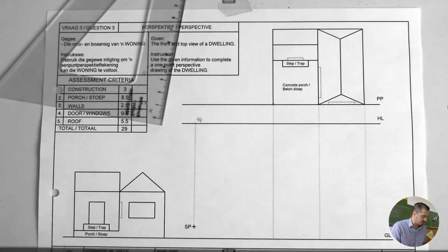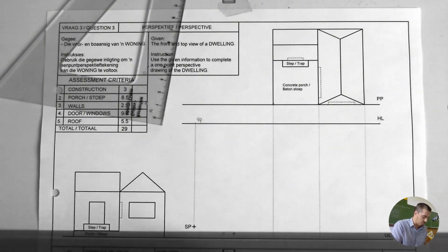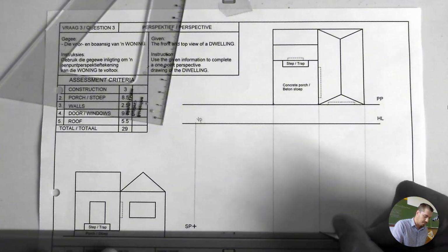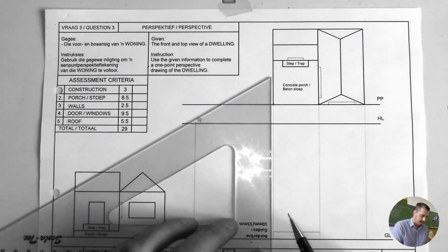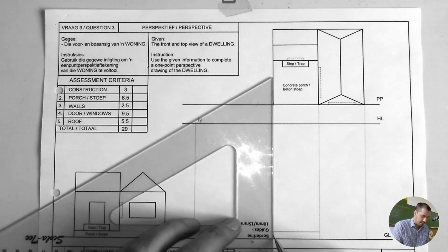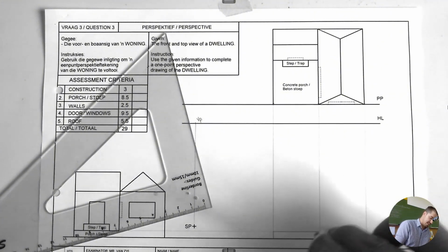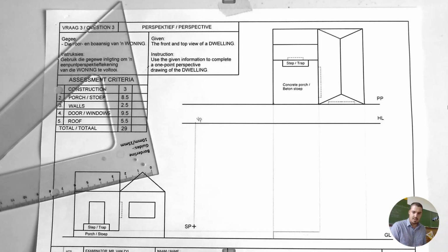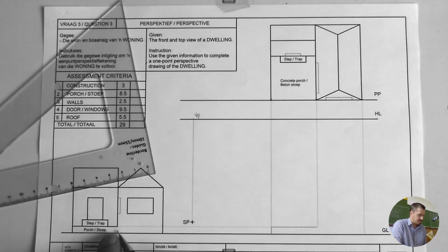So the height for the porch is always going to be gotten from the front view here. So you take the height, right? I'm lining it up with the first step, or well, the porch height, and I'm projecting this across. So drawing a line in there, you can see that is actually going to act as the starting point for my porch. So technically this line will not be here. How do I know this? That little line that's supposed to go down, because I can see on the front view, the pictorial view, it isn't there either.